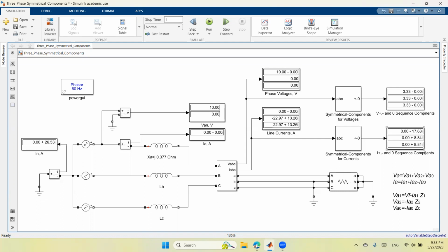0. If you add the zero sequence component plus A square times the positive sequence component plus A times the negative sequence component, you will get IB. And you can use the same relationship to find IC, but you need to add the zero sequence and multiply A by the positive sequence and A square by the negative sequence. So this is what we see for the double line to ground fault.